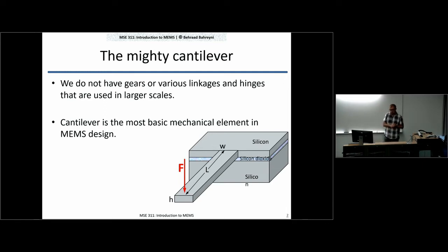Now, life is a little bit easier because your beams, for MEMS devices, usually have a rectangular cross-section as well. Rectangular because it's from a thin film that you etch using DRIE, for example. So you get vertical sidewalls on the sides and vertical sidewalls at top and bottom surfaces, a rectangular cross-section. It makes a lot of your calculations easier.